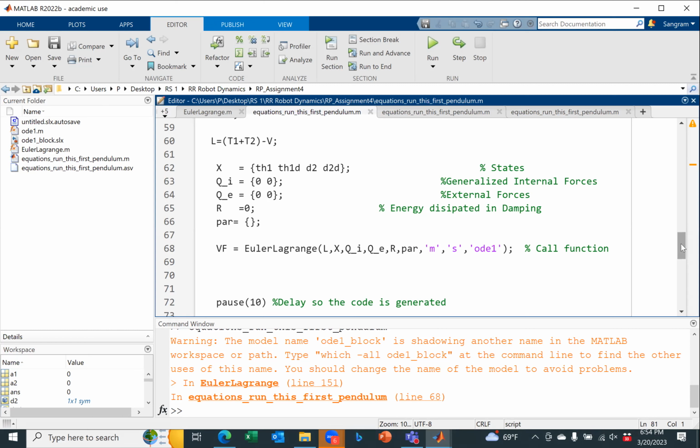Px is equal to, I'm going to call this, from here to here, D2, and from here to here, I'm going to call L1. So Px is D2 plus L1 cosine theta 1. Py is equal to D2 plus L1 sine theta 1. Pz is equal to 0.